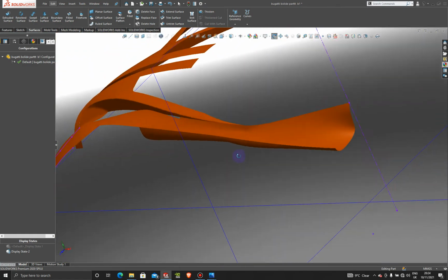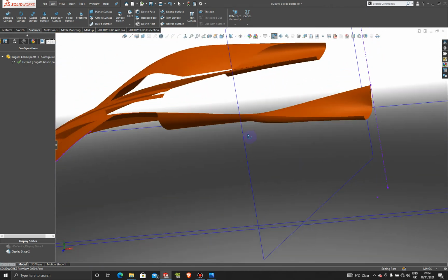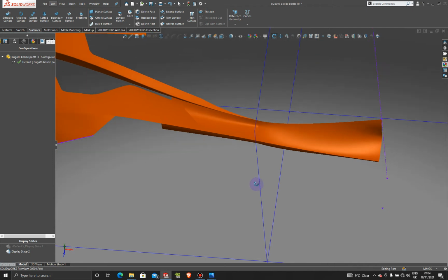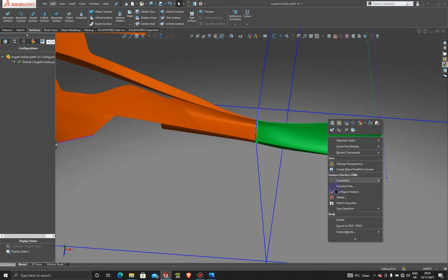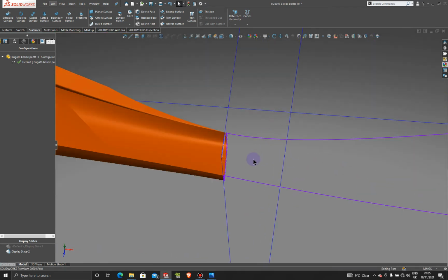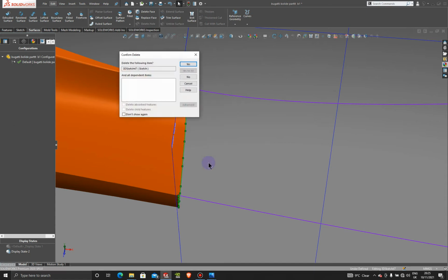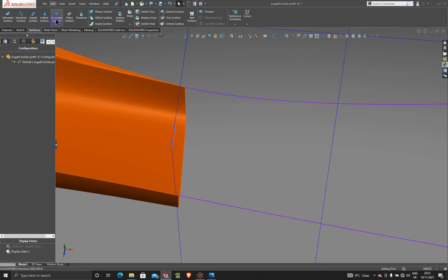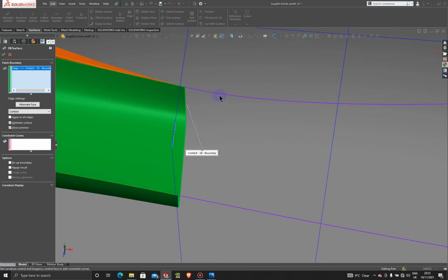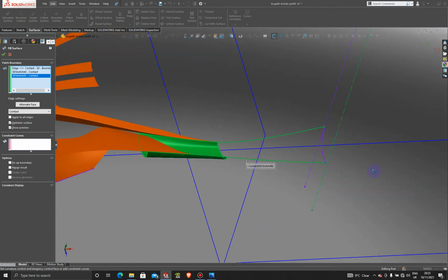All right. And then also the surface does not look good, because we don't have tangency. So let's delete that surface and let's do something else. Let's delete this sketch here. All right, and let's do a fill surface without that. So this surface, this one here, this one here, because we already connected these two edges over here that we needed.